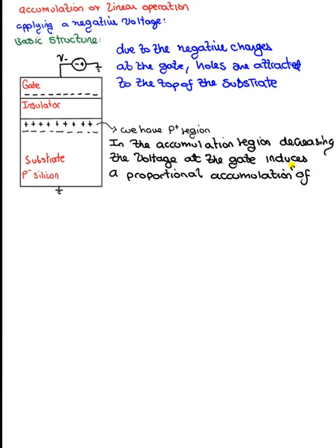So this is the key word, and that's why this region of operation is called that, accumulation of holes at the top of the substrate that I explained before.